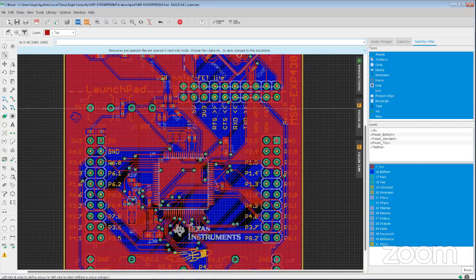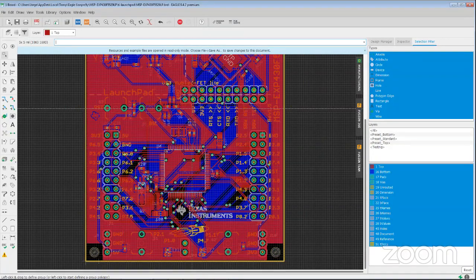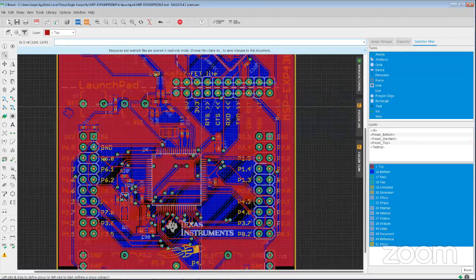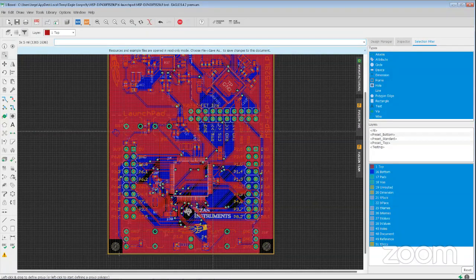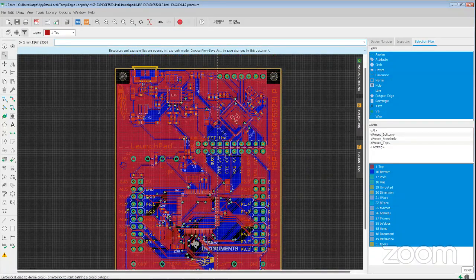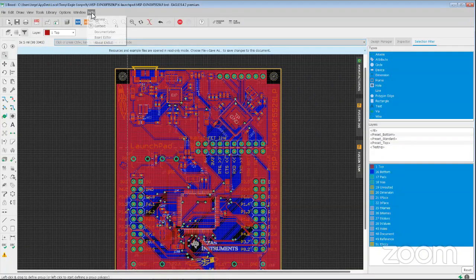So a couple of things. What can we do with the autorouter and the cost factors? Well, again, like I mentioned, you can guide the Autorouter if you want to try to stick to one layer, basically make the cost factor of the other layer super, super high so that the Autorouter won't want to get involved, won't want to switch to the other layer. And you can see what the cost factors represent.